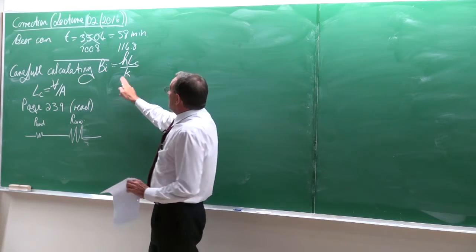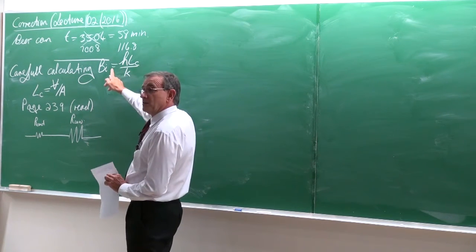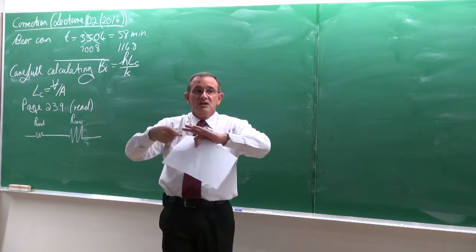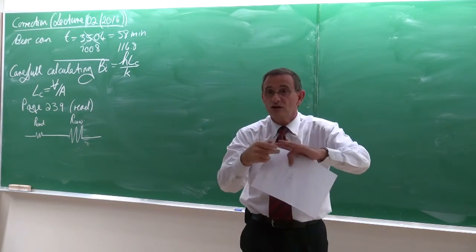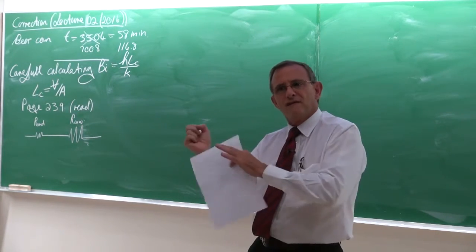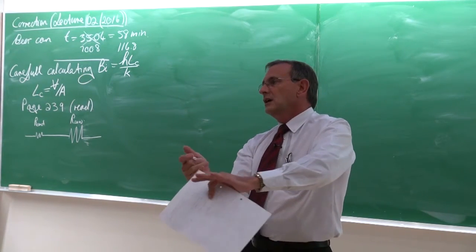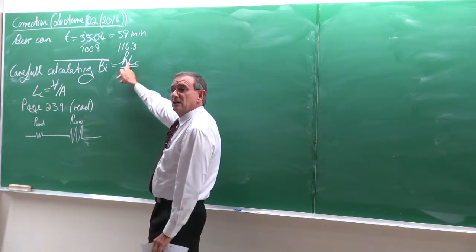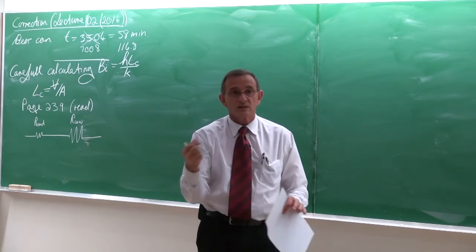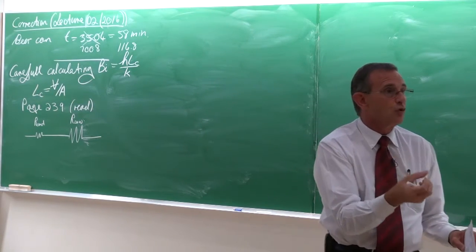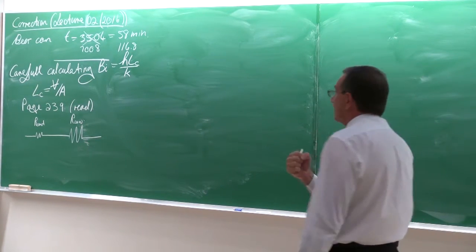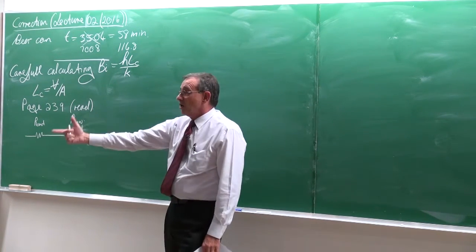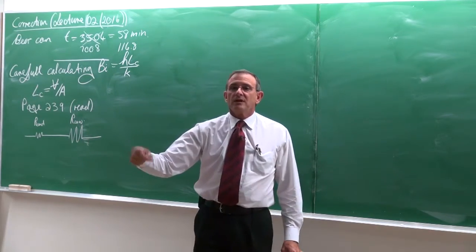When will that be? It will work well, typically the lump system approach, when the heat transfer coefficient is small. So normally the body is exposed to an environment of natural convection. There's not a fan, it is not moving at a large velocity or anything like that. That's the first thing. The second thing is the characteristic length must be small. So it must be a small geometry and a small object. And the third thing is the thermal conductivity must be very high. So stainless steel, copper, etc.